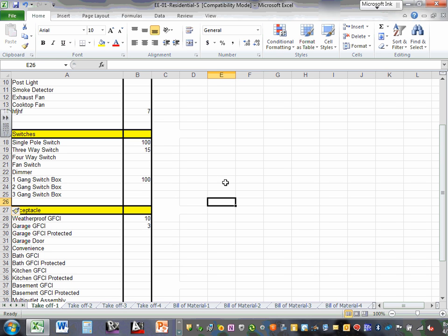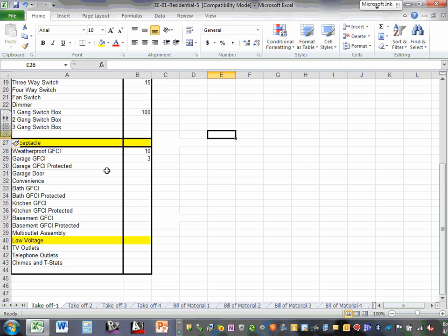And you look at the schedule. Derek, remember the schedule. If the circuit is a 20 amp circuit, that will be 12. If the circuit is a 15 amp circuit, that will be 14. So please look at the schedules, and you guys have the schedules. Okay, so here's my again.